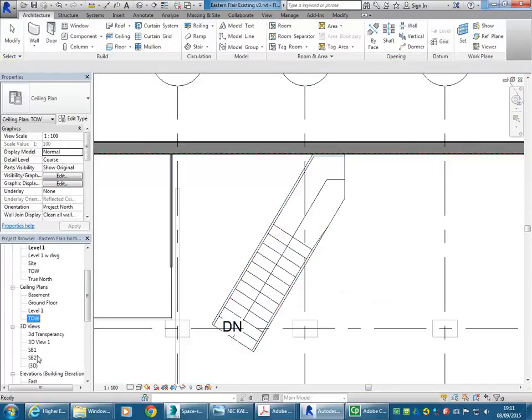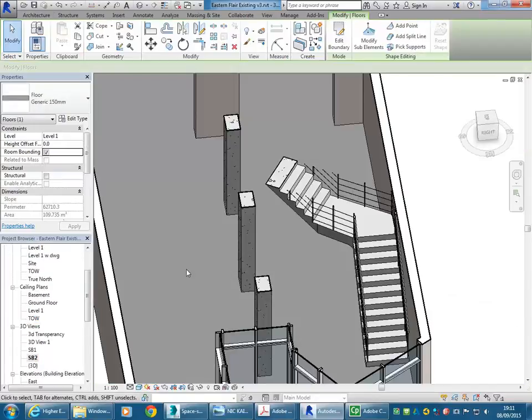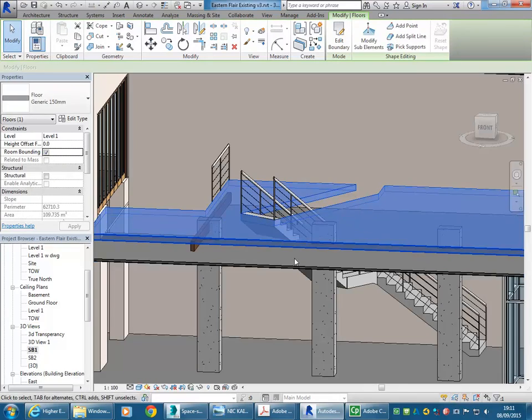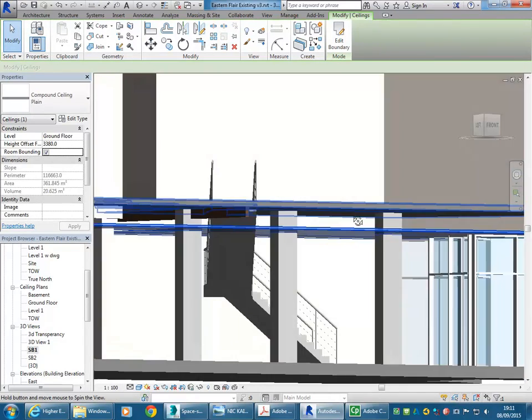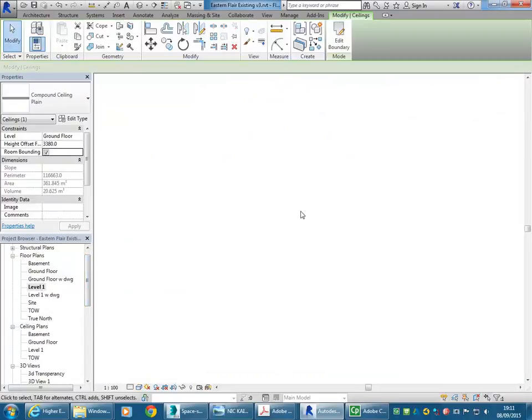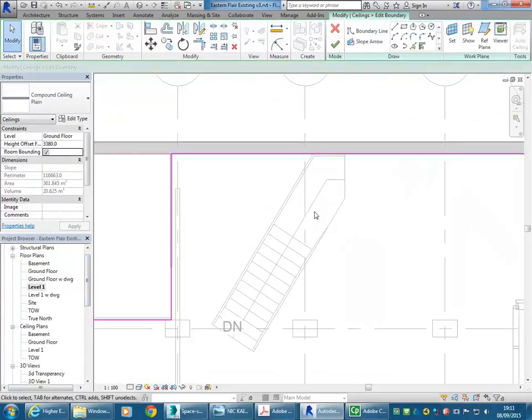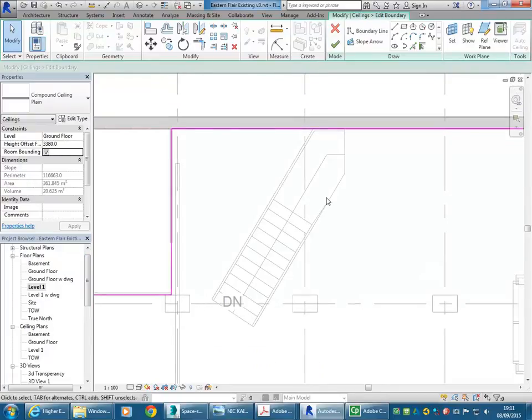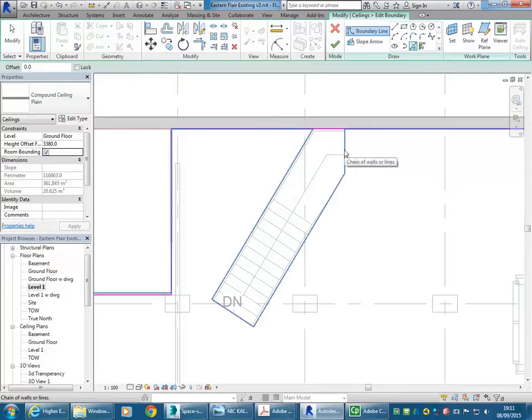Okay, so then I've got the ceiling needs a hole in it as well. But I can just use the shape of the floor. I don't need to go and choose those same edges again. If I use tab, it should give me, in fact it will give me the outline, but I'm not going to use that because it will choose the outer edges as well, and I don't want that.